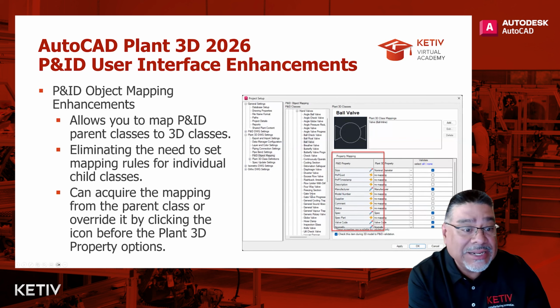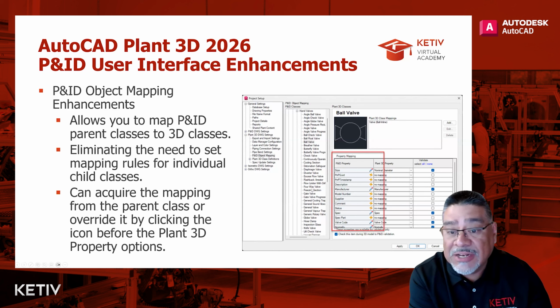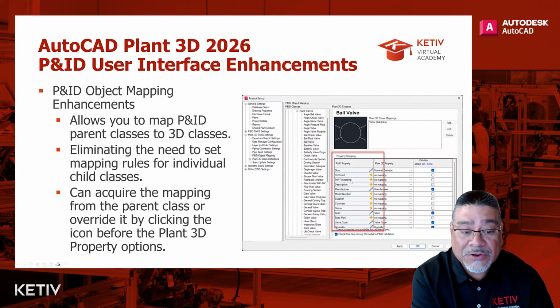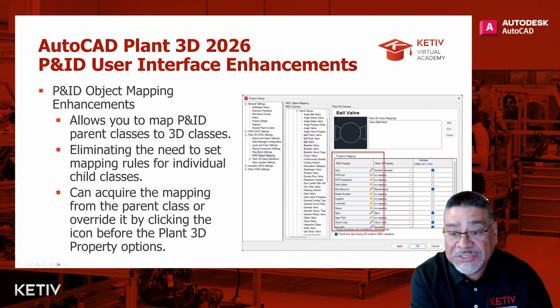So this has eliminated the need to set mapping rules for individual child classes, that wasn't available, that you'd have to go through previously. And also you can acquire the mapping from the parent class or override it by clicking the icon before the Plant 3D property options. So these little icons here, you could still go through and override if needed on some of these items as well.